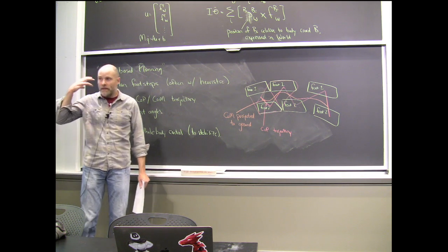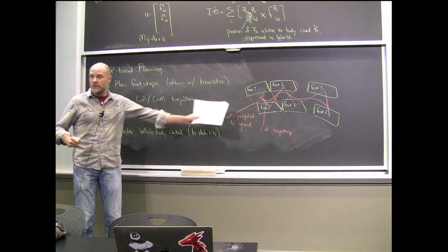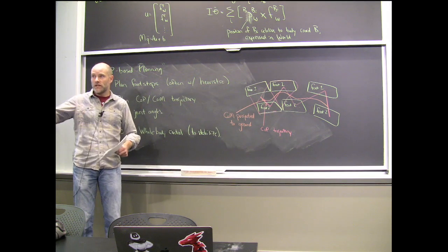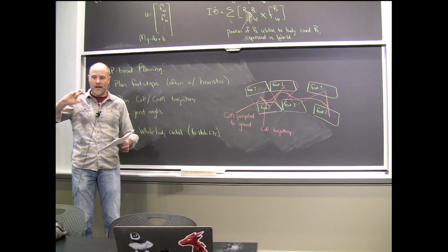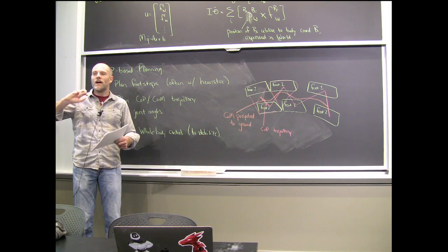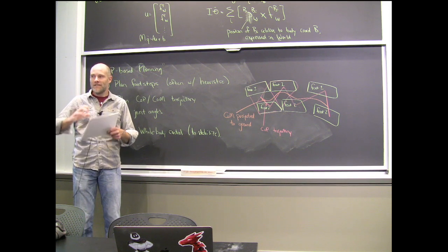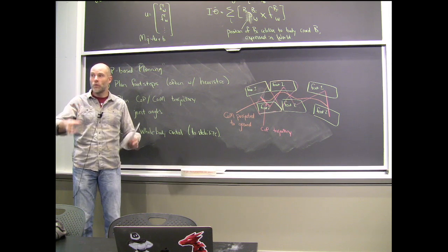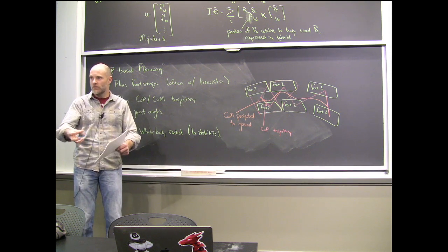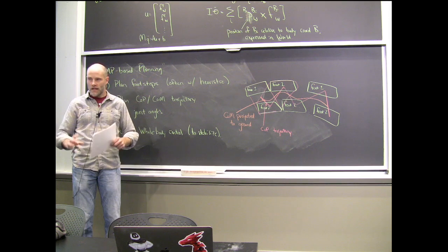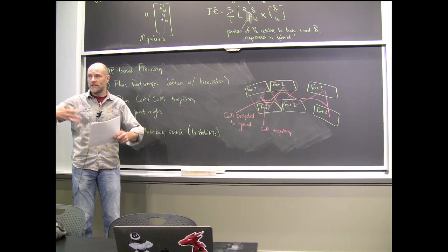But I actually think that picture is very important. We've moved the complexity of the nonlinear dynamics into a more explicitly discrete set of decisions with simple continuous dynamics. And this was a mind shift for me over the years, right? I was very interested in nonlinear dynamics. And I think as the problems got harder, ironically, the nonlinear dynamics mattered less. And the discrete decisions about when you make contact, where you make contact, were more important to task success. Certainly for manipulation, that's true. And even for walking, that became true. So I slowly shifted my mindset to thinking about it a bit more like a combinatorial problem and less like a continuous nonlinear optimization.